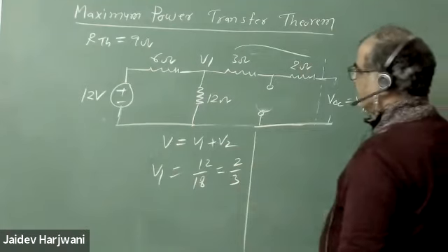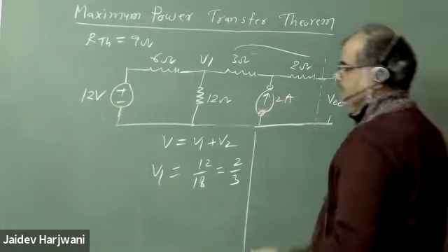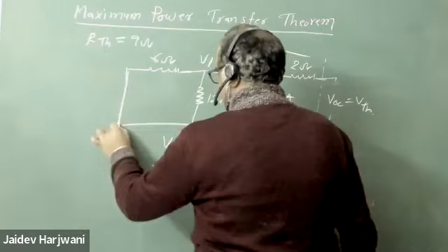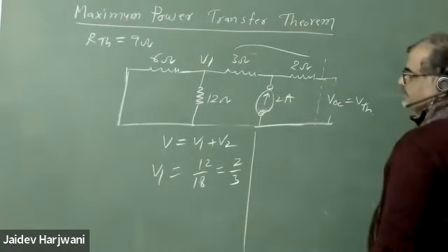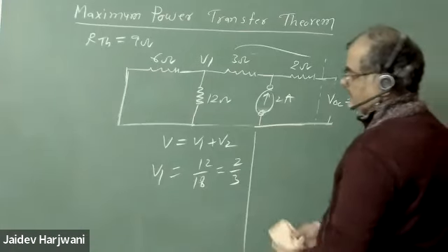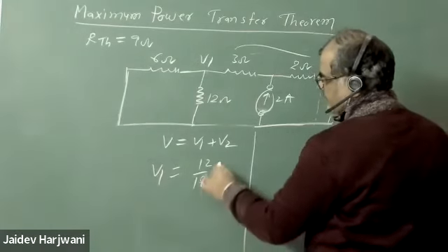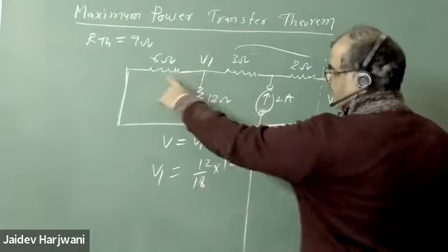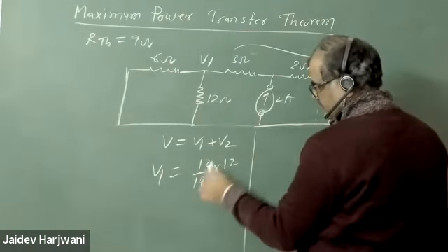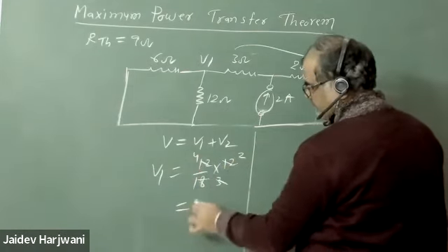Now let me calculate for this current source, 2 ampere. So for the 2 ampere source I need to short this one. Now if we short this one, yes, sir, V1 into 12 will also be there, 12 volt will also be multiplied. Okay, so what have we done now, we have only found the current so far. Yes sir, 12. Okay, so now how much will this come? 8. 6 2, 6 3, 6 4, 8. Thank you very much. 8 volt.